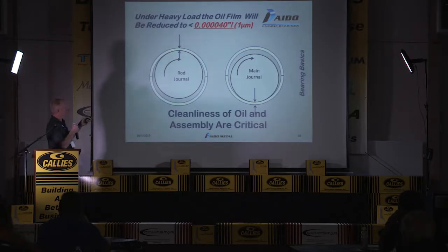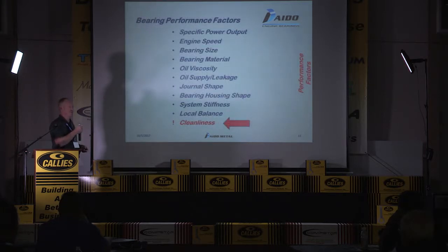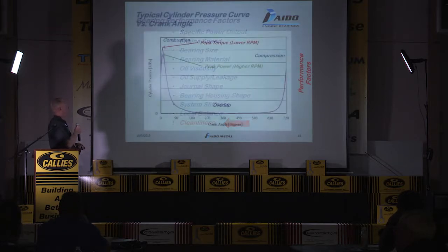Back to this point right here, this is why cleanliness is such a huge factor. When you get down to 40 millionths of an inch, it doesn't take much of a piece of debris to disrupt that oil film and start to do damage to the bearings.